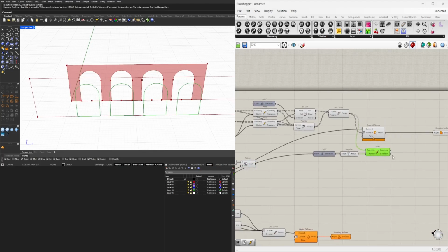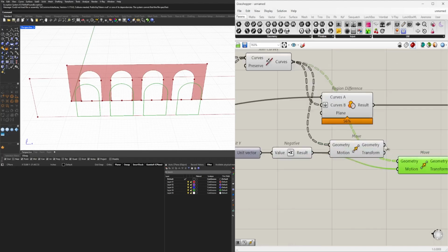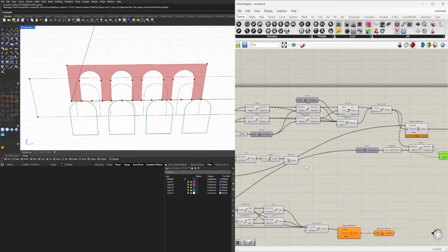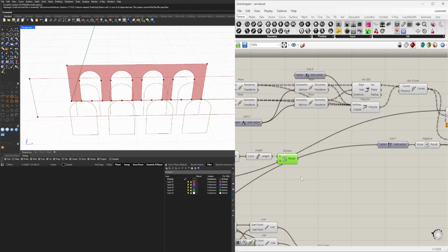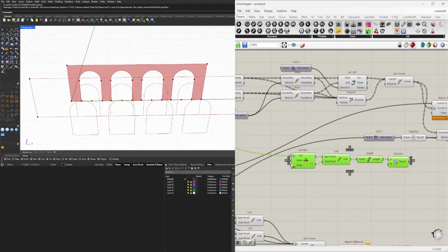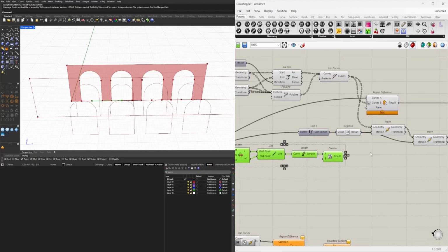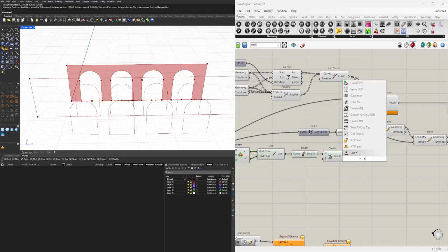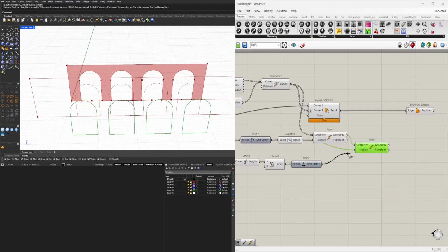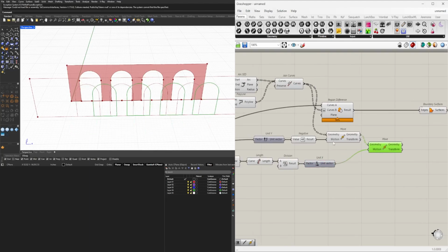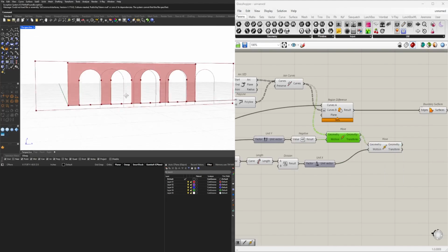Now that we have this moved forward, we need to move it again, but in the X direction. So I'll copy this, tap Alt, plug this in, and now we're going to be using this number. That is that line segment divided by 2, but now we're moving that in the X direction. And now we can shift those by half and disable the preview before.